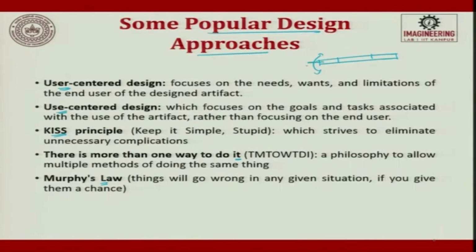But now what has happened, they realize if you start swinging, it brings a lot of fatigue to the person who operates the stick. Now, these movements are replaced by using Wi-Fi sensors or ultrasonic sensors, ultrasonic for sensing at the bottom and Wi-Fi to communicate with the existing location where he is, and that in turn connects to the operator and he knows where he is currently located, how far he has to move. This Wi-Fi is to tell his current position and movement. Ultrasonic is within the short vicinity whether there is an obstruction or not.